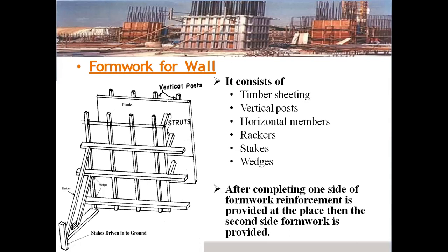These rackers, stakes and wedges here, these are the rackers which help in the balancing of horizontal members which is supported to the timber sheeting, and these are the wedges, the posts which are provided for the timber sheeting, and stakes driven into the ground to support these rackers, which give perfect support to the rackers we provided.